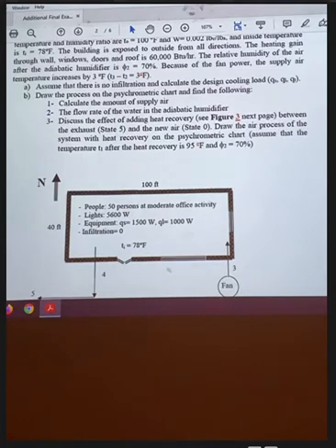In this case, we are given the heat gain through the building construction, windows, doors, walls, roof. So what we need to add is the load from people, from light, and from equipment. Infiltration here is given equal to 0. So there is no infiltration. That means the building is set at higher pressure than surrounding. That means this building is pressurized. That's why there is no infiltration. So we need first to find the cooling load.